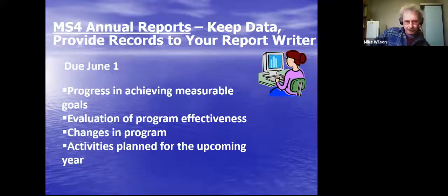Let's review. Your MS4 annual reports, municipal separate storm sewer systems annual reports. What do you have to do? You've got to keep data. There were recommended categories and suggested categories and required categories. So you must provide records for your report writing. And all of those reports are due June 1st.